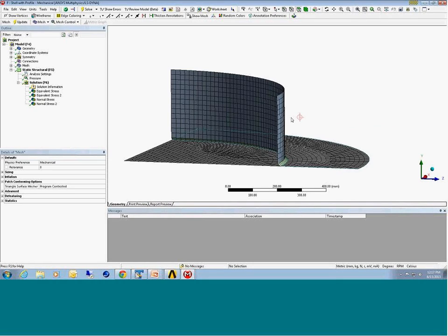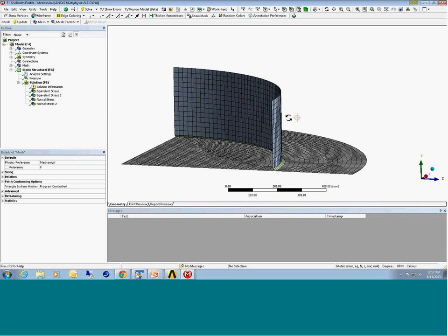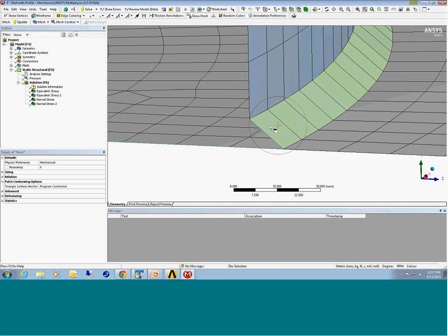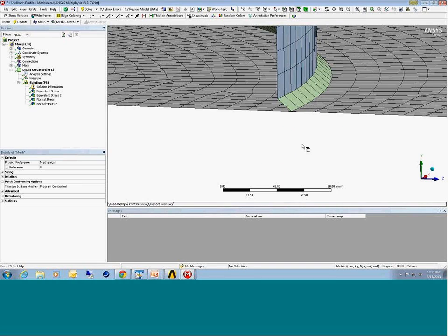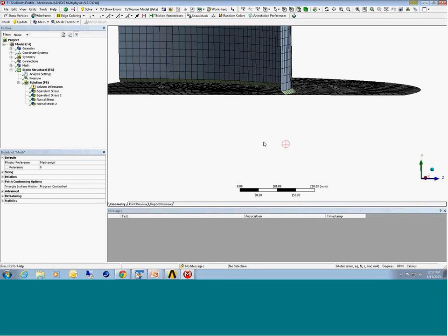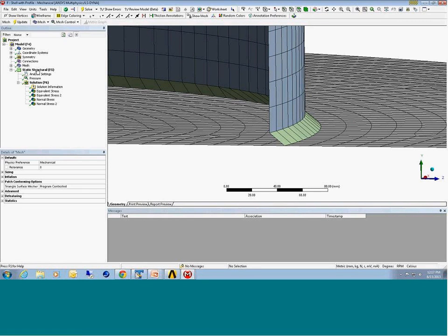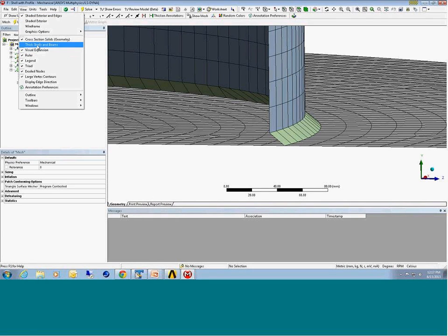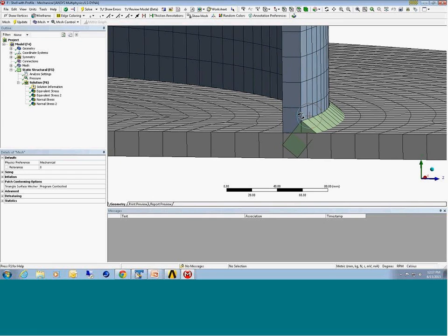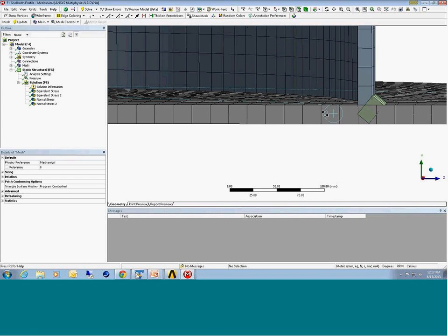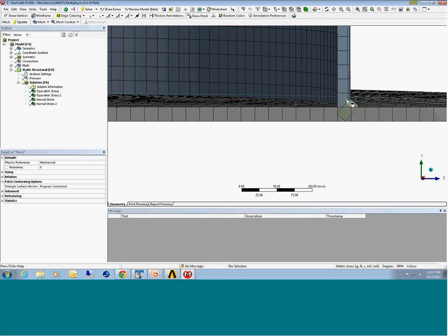Same problem I just talked about before, only now I've modeled it with shell elements. And now what I've done is modeled the weld profile with a diagonal shell at the weld intersection. And I had to define some kind of thickness for that shell. And what you can do in ANSYS is go ahead and say, in the view process, go ahead and show the actual profile. You can notice that I made the thickness more or less line up sort of with what the weld profile would look like.